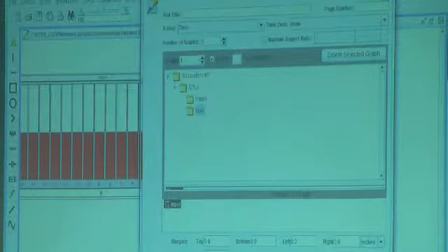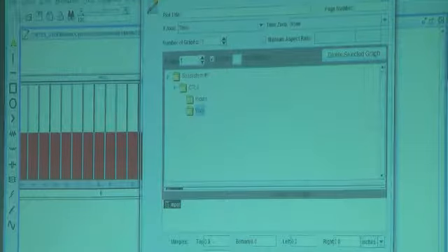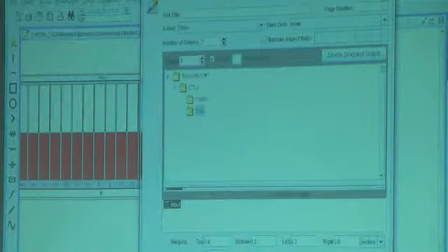And then if I want to see 8 bits, what should my mask be? It's a hexadecimal number. Remember before we only wanted to see 3 bits? We put 7. So 3 bits, if you think of 3 ones, that's 7.